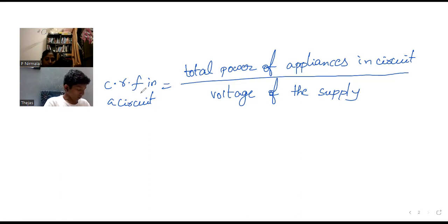That means 25 milliseconds. After repairing the fault in the circuit, the MCB is then raised up. So MCB is more convenient than fuse. It avoids the inconvenience of connecting a new fuse wire, and it is much safer due to the quick response. In olden days, definitely we had to remove that wire and put in a new wire, then only it would work. But now the MCBs automatically trip.